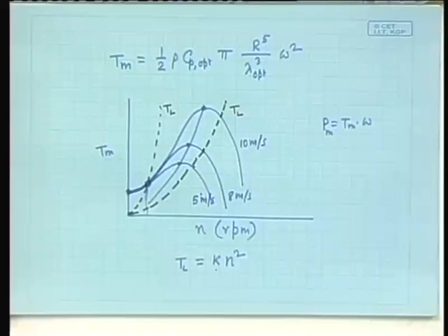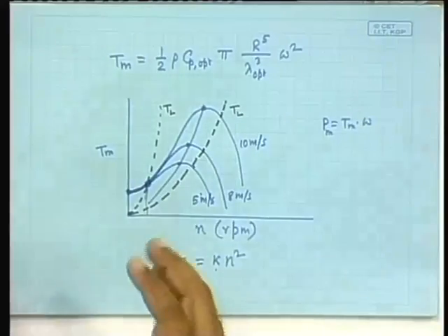So, you see, it is not only the pitch angle that needs to be controlled, it is also the characteristic of the generator that needs to be controlled, and the torque ultimately depends on whether you can control the power that goes out. If you can control the power that goes out from the generator to the load, then there is a speed of rotation.